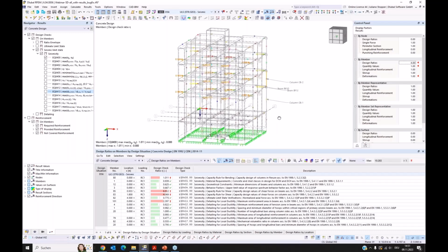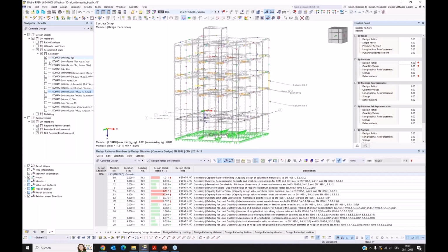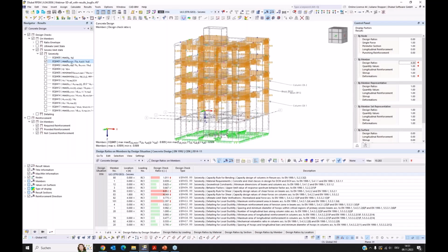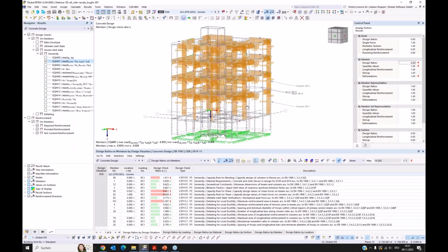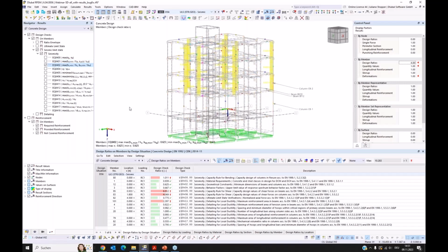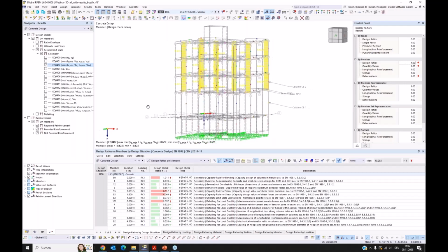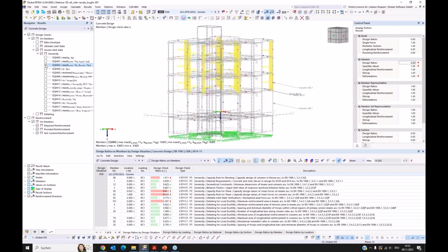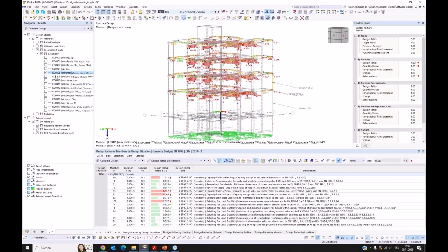So here we have the strong column weak beam rule checked for the nodes. Then we have here the material checked for all members, and we have the geometric rules checked. And yeah, I checked the behavior factor just for one, but it's valid for all the building. Only I did the calculation just once.